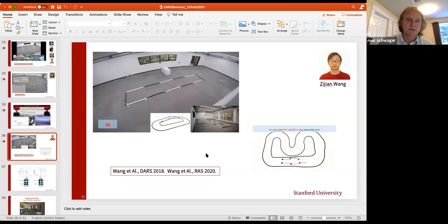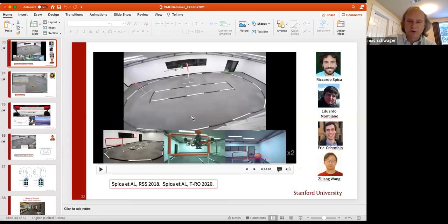So actually in these drone racing examples, we're doing that. I didn't talk about the perception piece here, but we're actually doing this. Both of the robots have a forward-facing camera, and that camera is visual servoed through the yaw mode of the drone to always look at the other drone. And then they pick up these colored balls.